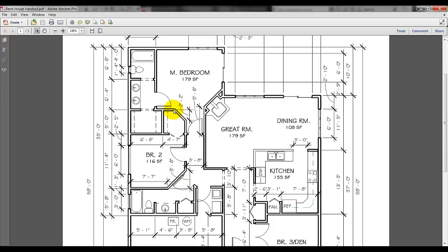Any angled wall is 45 degrees. The angles are probably the most challenging part of the plan, but just do your best to get them laid out. Ultimately, I would not worry about getting every wall placed exactly within a fraction of an 1/8 inch, of a 1/16 of an inch. We're looking more at whole numbers. As long as you're within that realm, I think we'll be in good shape.